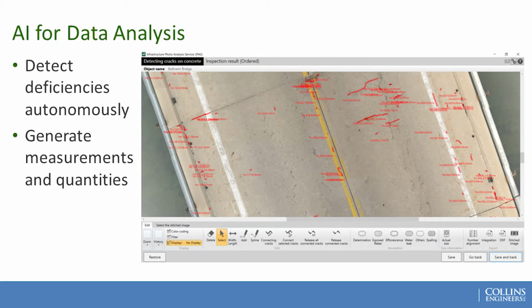We've been using a software from Fujifilm and also from Bentley to do the automatic crack detection. Usually the way it works is it will sometimes maybe overestimate where there's cracks, but it's really easy to just go in and delete the ones that we know aren't cracks. And in the end, it's far more accurate than somebody trying to measure them in the field. And again, then we can compare them on future cycles.